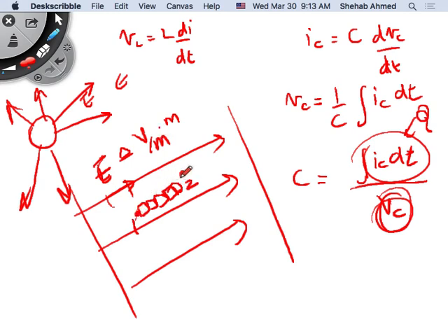If I calculate the voltage difference between 2 points, I can bring 1 point on my conductor and 1 point on another conductor, or 1 point on my conductor and ground, for example, right? And that way I will be able to calculate the capacitance between two conductors, or the capacitance between conductor and ground. If I calculate the capacitance between two conductors, this is due to the voltage between the two conductors, V1,2, right? This is the voltage between two conductors.